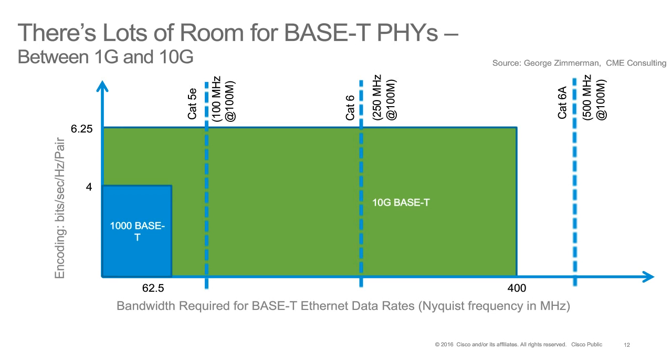But what if we took what we knew about 10GBASE-T, because we standardized that 10 years ago, and we know how to make that build. What if we took that and ran it at a quarter speed? I could slide 2.5GBASE-T in, pretty much with the same 10GBASE-T encoding, at 100 megahertz. I could then slide down 5GBASE-T at around 200 megahertz. And what we're seeing is it's technically feasible to get more bandwidth over the cable that exists in the world today.